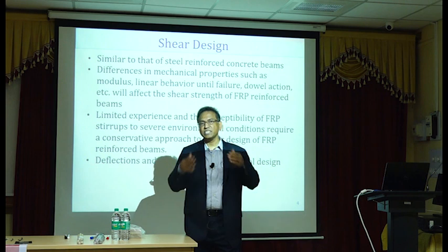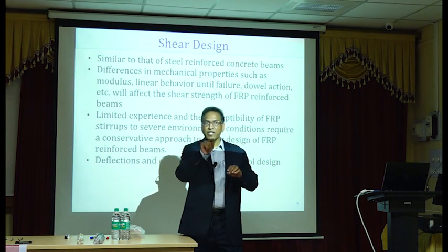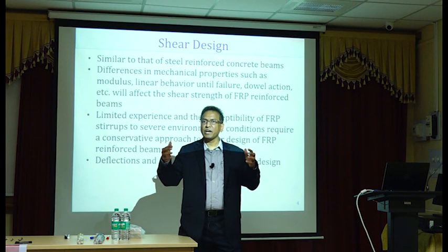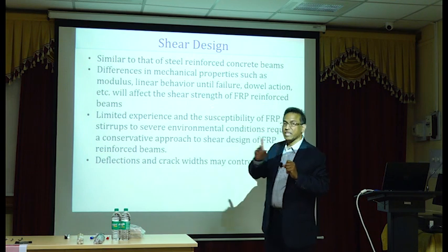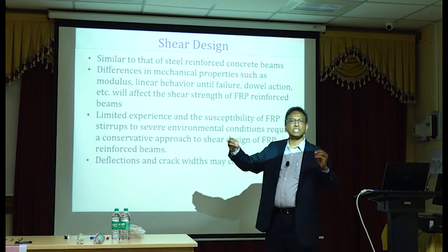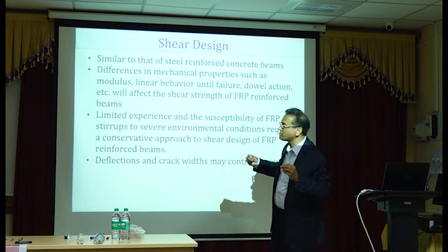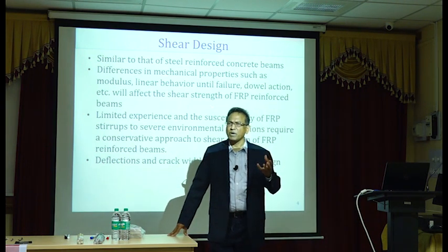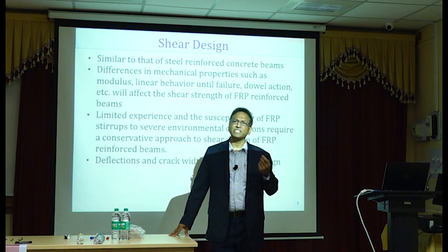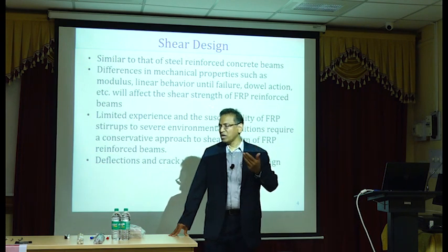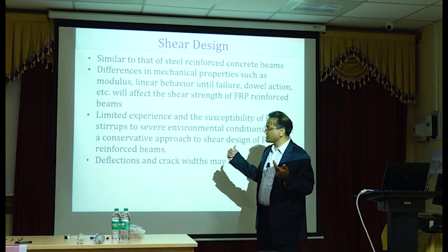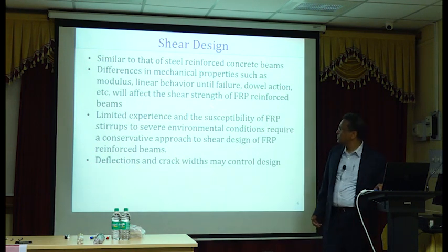So shear design is based on compatibility of the diagonal crack and then the widening of the diagonal crack. If you have, let me go to the next slide and then I will explain that better. So that's a big problem. You are stretching it much more than you stretch the steel bars. Concrete can only stretch that much, right? After stretching a little bit, I have to define what little bit is, it will start cracking. So excessive cracking can also be a problem in terms of spalling. That's one. The other problem is, we'll go to the next slide and that will be very clear once I show you that slide.